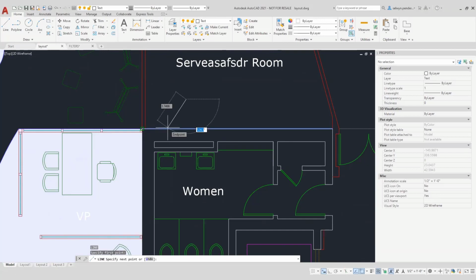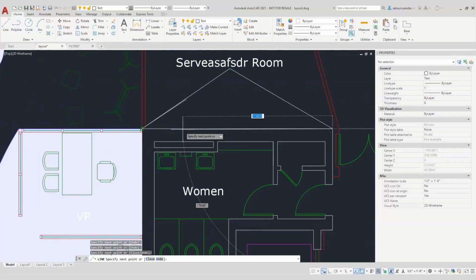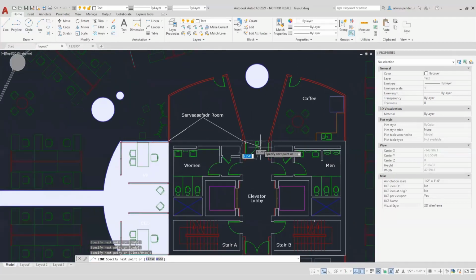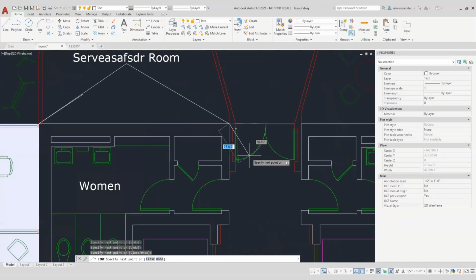If I press tab, keep on pressing tab, I'll be able to select the O-snaps that are available for that line. You can see that I've got the green one up here, and if I press tab again, I'll be snapping to that end. So snap up to this end, I'll come back here, and I'll press tab again and click here, and you'll see that it snaps to the other end. The same thing with circles and arcs. I can come down here and I press tab and it will cycle through the available snaps.